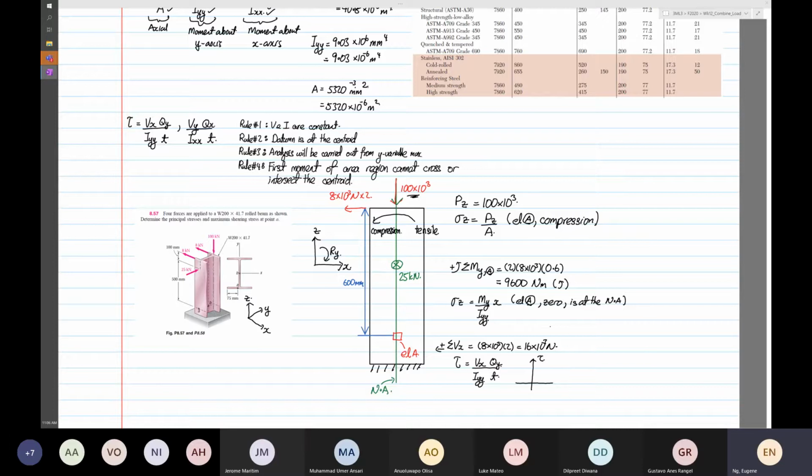So this is now our x direction. The shear stress will be at the maximum on the neutral axis. If the element is over here where I'm drawing now, this is element alpha. The shear stress will be equal to what? 0. Yes or no? But if it's not at alpha position, is at element A the position, you're going to have a maximum shearing stress. So we will write down here, element A will observe tau max.